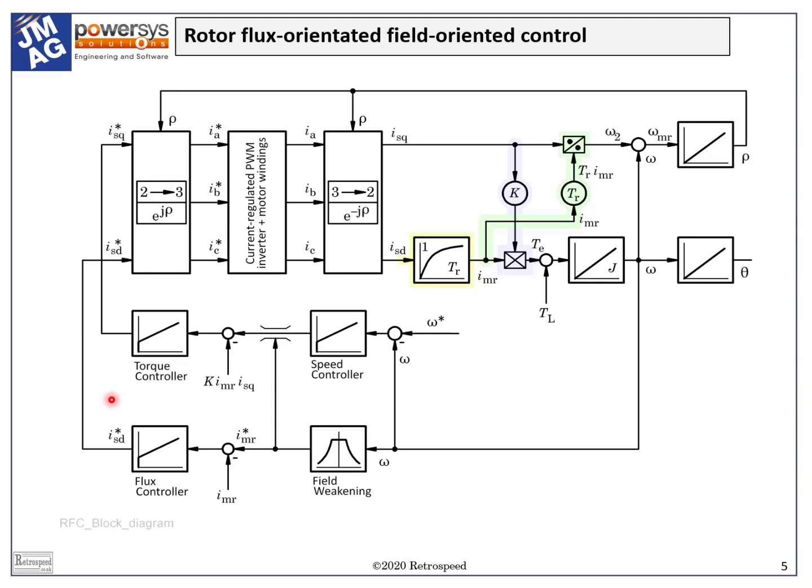Let's look closely. Here we see three currents IA, IB, IC, real numbers whose values are the actual instantaneous amperes flowing into the respective motor windings. They are measured by current transducers located in the output leads of the inverter and therefore in series with the motor windings.